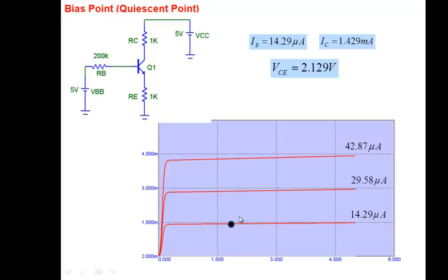So what I'm trying to tell you is, RC for 1K is here, and you're tempted to increase gain. So it comes here for 2K. Then you go 3K, it comes here. Then you go a little bit more, and then suddenly what do you see? Instead of gain going up, gain just drops. From 150 or 200, gain drops to 1 or 0.5. And why does it happen? Because your transistor has gone from active mode to saturation mode. Graphs like these help us to visualize what is happening to my operating point.